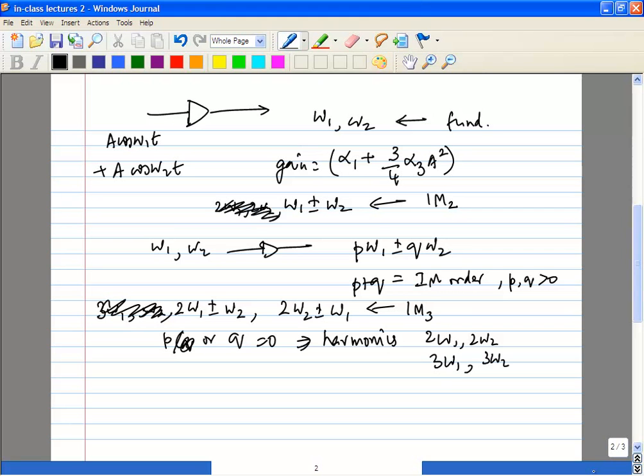If you take an amplifier which doesn't cut down things outside its bandwidth, then you would get a much truer picture. So that kind of definition is meant to be used with broadband amplifiers. If you take filters, assume it's very nonlinear but has a very sharp cutoff, it looks as if it's very linear, but in reality, inherently the system is nonlinear. So sure, you can back calculate it.